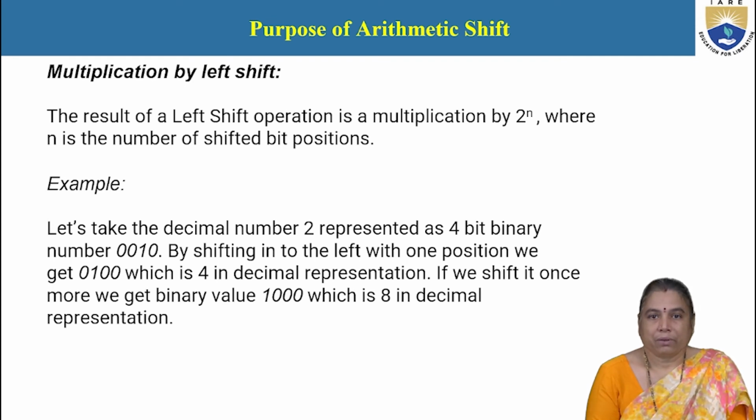What is the purpose of arithmetic shift? Arithmetic shift is generally used for multiplication by left shift. The result of a left shift operation is a multiplication by 2 to the power n, where n is the number of shifted bit positions. Let us consider an example.